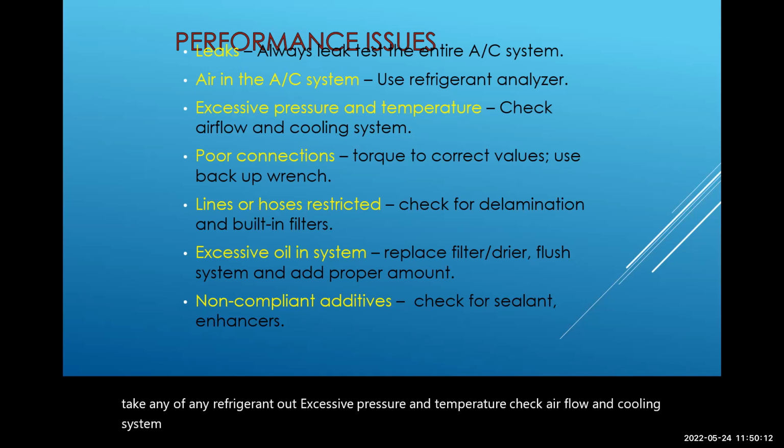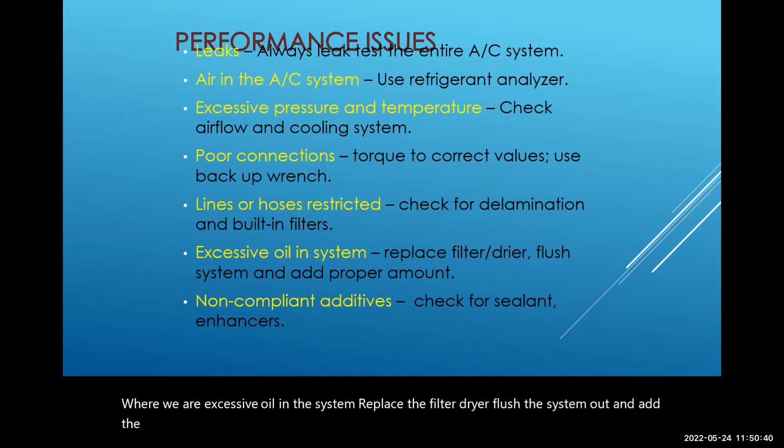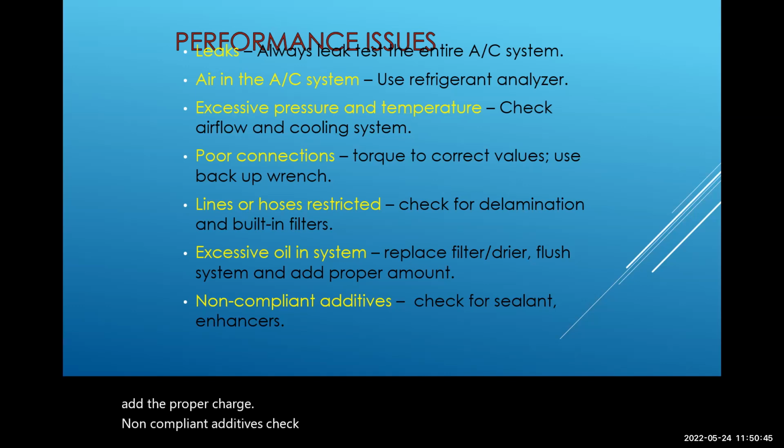Poor connections: torque to correct values, use the backup wrench. Lines or hoses restricted: check for delamination and buildup in filters. Excessive oil in the system: replace the filter dryer, flush the system out, and add the proper charge. Non-compliant additives: check for sealants, and there's a sealant tester that you can use too, and any kind of enhancers that you may want to put in there also.